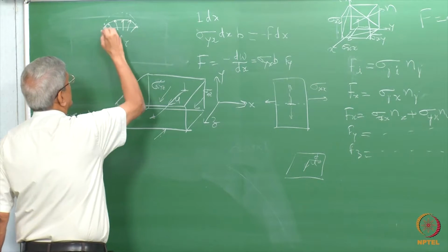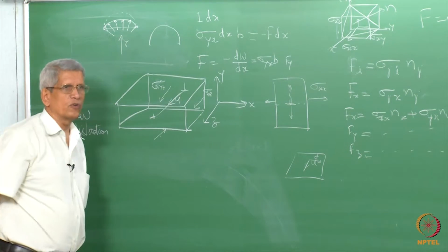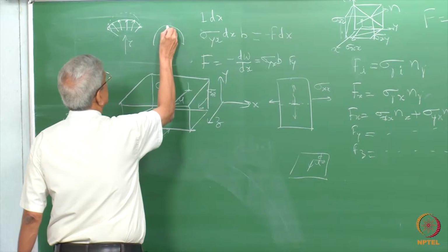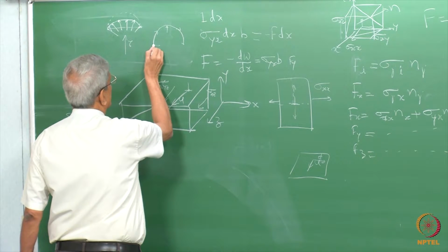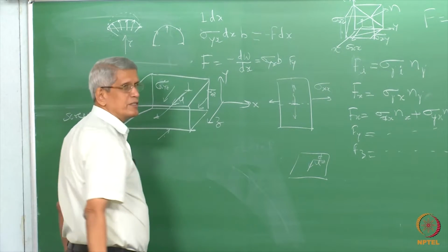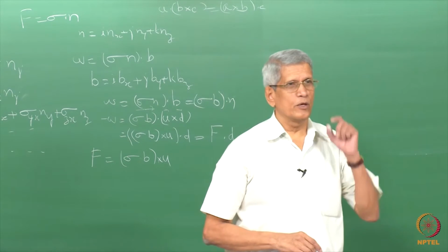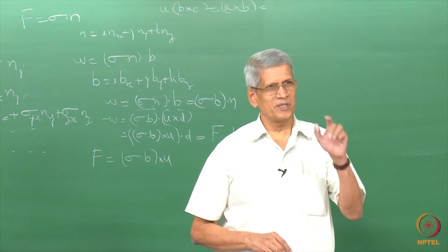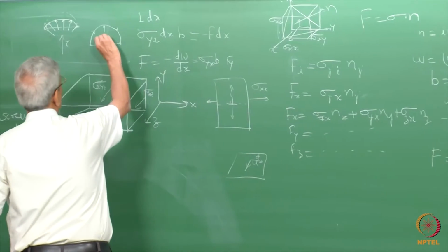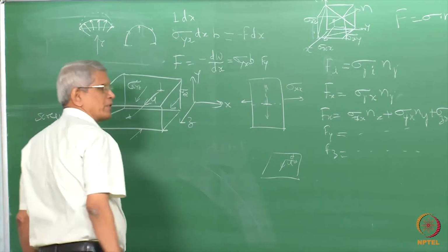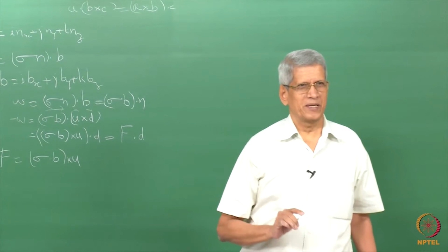This is the direction. When it becomes a semicircle, how will the force act? The force will be acting here in this direction on the dislocation, but at this one it's being pinned, and the force is acting in this direction, perpendicular. So when that happens, the dislocation moves in the direction in which the force is acting. So now the dislocation can try to bend around this. That is what makes the dislocation form loops around precipitates.